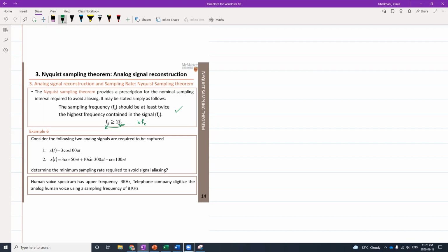And those with higher frequency, about 2 kilohertz, are good too. Anything with higher frequency will be more expensive. Why? Because they are going to have a faster processor to do the method of successive approximation that we have discussed earlier. That's the reason those with higher frequency are a little bit more expensive.